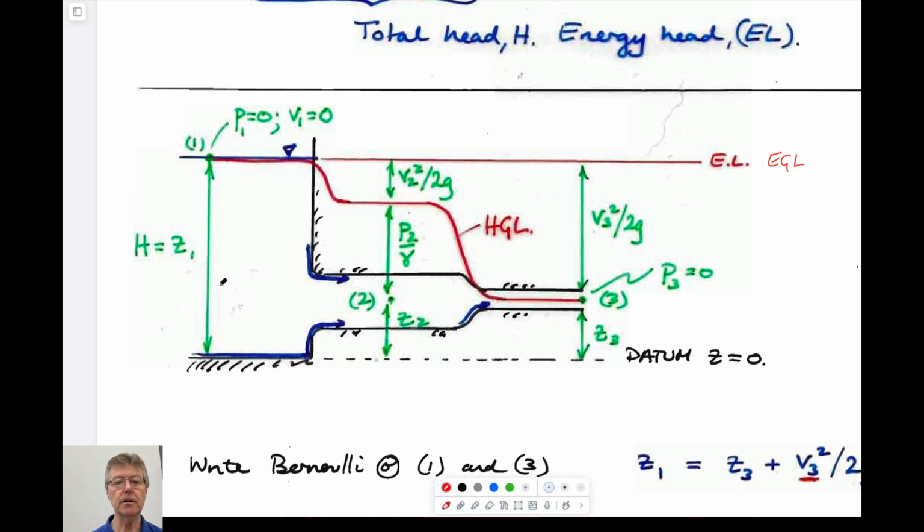And if we look at this behavior as we're upstream, we have a hydraulic grade line. We said before that the hydraulic head is equal to the pressure over the unit weight plus the elevation. We do these because all of you who are dealing with fluid flows in the ground, environmental systems engineers, petroleum engineers, energy engineers for geothermal as well, I guess, and mining engineers a little bit for groundwater.